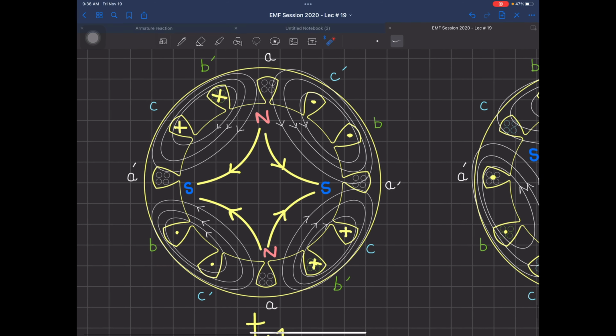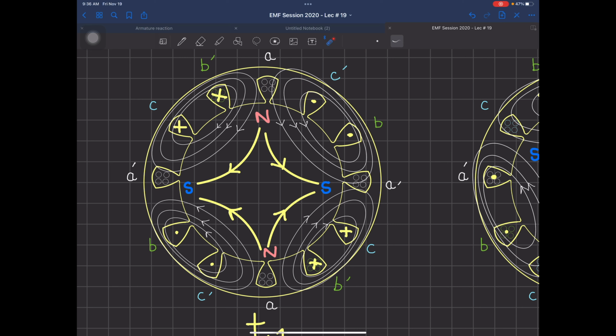Now, when all of these are done, this is the most difficult part of a 4-pole machine. Now you see over here, you have 4 poles. How? You see this cross and cross. I've not drawn their individual fluxes, but you use your right hand rule, and the flux direction is like this. So flux is flowing over here. This part is empty, it's not producing any flux. Similarly, this is dot, so this will be coming out, fingers curled in this direction, so flux flows like this. Similarly here, and similarly for this one. So you have now 4 poles, each with north towards south.